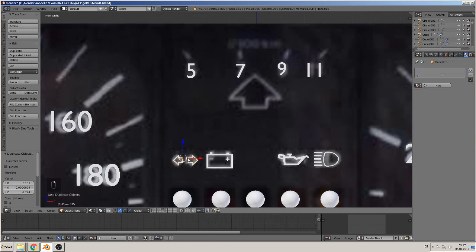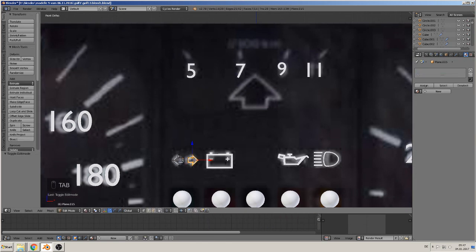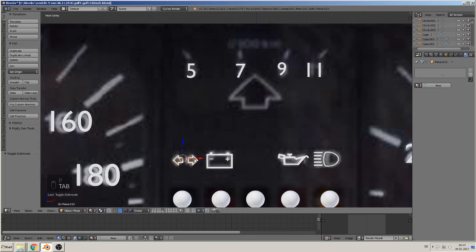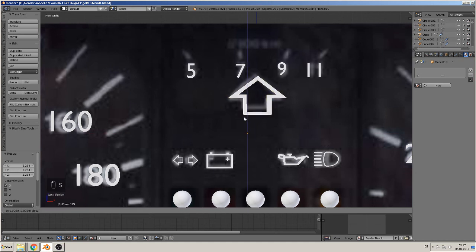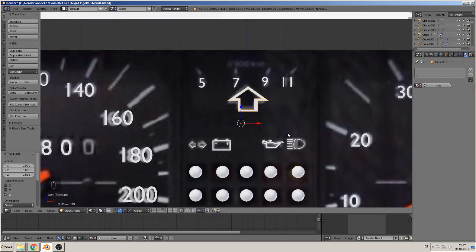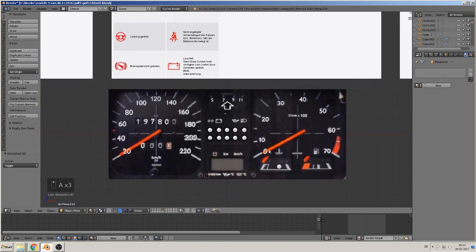That means we take that and make a copy of it, Shift D. Then we press P to separate the selection. Now we have a single arrow and can rotate Y90, rotate Y180, scale up, grab, scale on the X, a little bit in the set. So we have that too. You can make that perfect if you want. For me, that's okay.